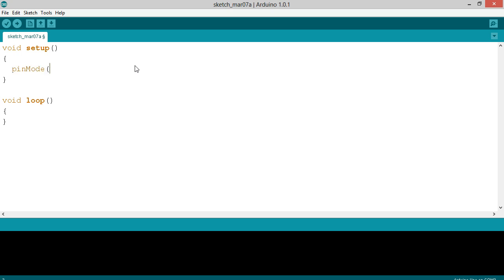So we're going to start with the pin mode again. Make sure that we can enable the mouse device to start and stop when we want to. So I'm setting pin mode 2 as an input and setting its pull up so that we can just connect pin 2 to ground to start the mouse device and then remove it when we want it to stop. And then I'm going to say random seed. Random seed is the function you call to seed the random number generator, and I'm just giving it a random value to seed it with, and that's the millisecond timer or whatever it is at this point. So it's random. It should make the device behave differently every time you power the device, because we want this to act randomly.